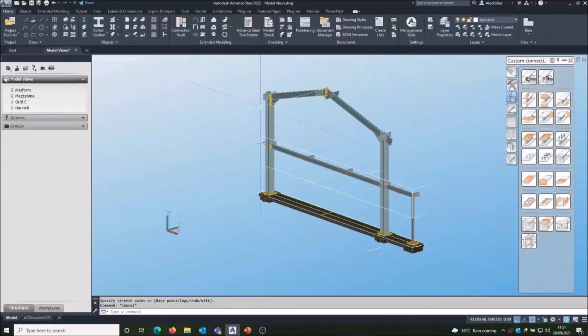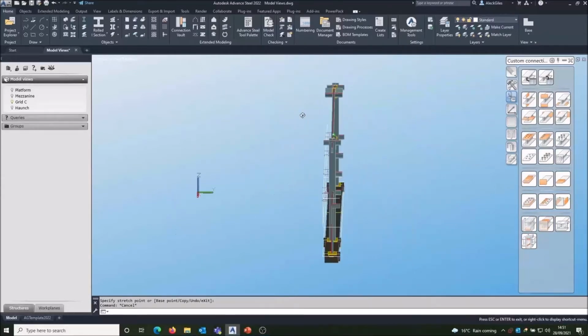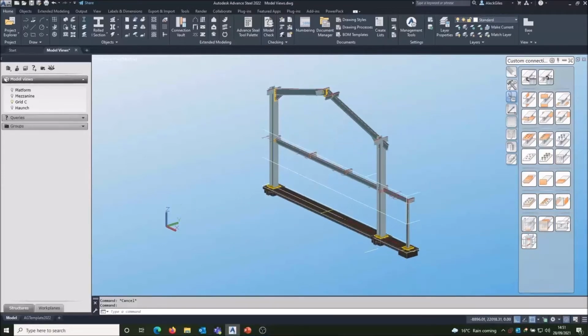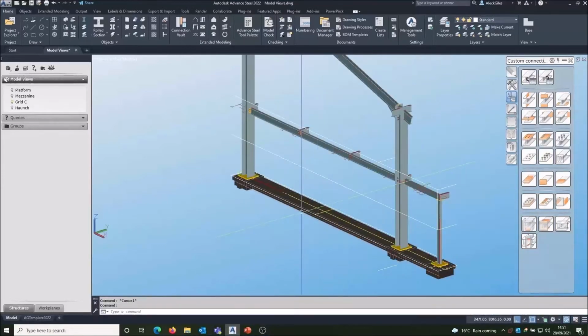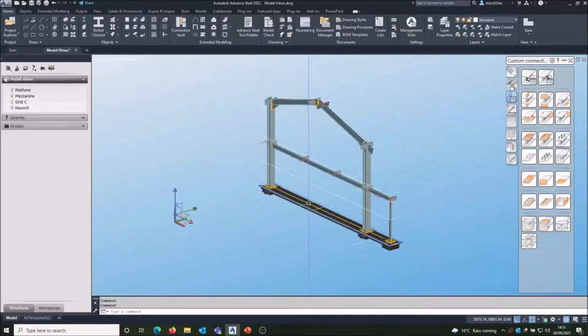On the grid one, the grid box automatically covers 500mm all around the end of the grid, so it's 1 meter wide, and it's got an infinite Z depth, slightly different to the others. The Z direction is infinite, so there's no limit on that, but in the X and Y direction, it's giving you 500mm margin around the end of the grid line.